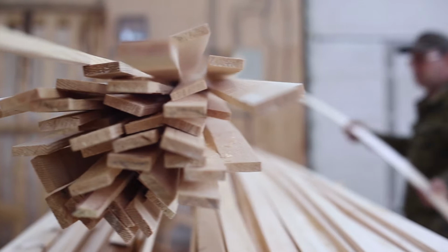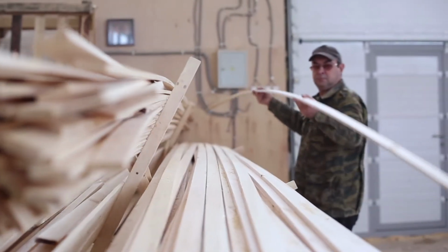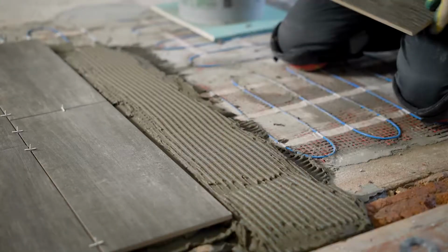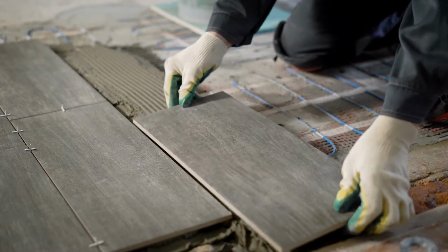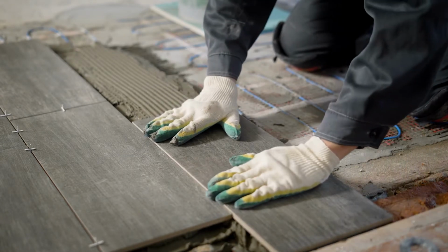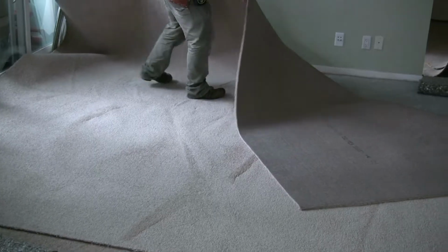Do you really need a material? For example, does a floor covering such as carpet or floor tiles have high embodied carbon? How often will it need to be replaced over the course of its life? If carpet is placed on concrete, it greatly reduces the benefit of thermal mass. Some flooring materials can work well as the finished product without a floor covering, for example polished concrete or timber floors.